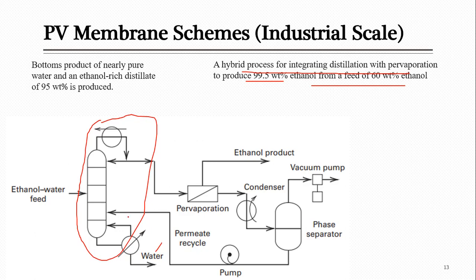Okay, you have separated some water, and from the top you will be looking for the lighter component, ethanol, to be obtained as your product. You are looking for a product of purity 99.5 weight%, but here its purity is 95 weight%. Even if you install this distillation equipment, the maximum you can reach is 99.5 weight% ethanol-water. Above this, an azeotrope is formed and you can't separate further.